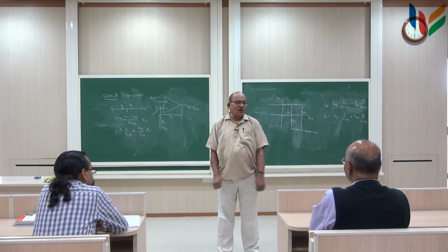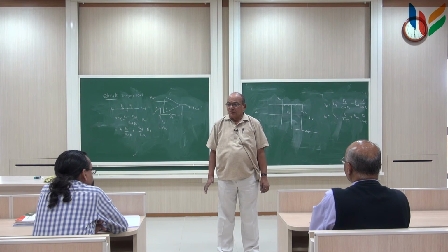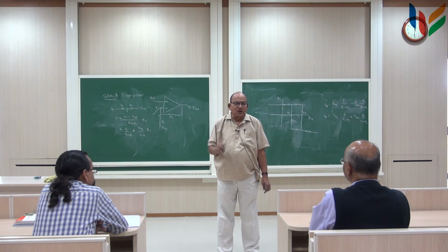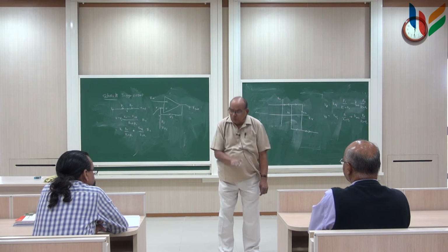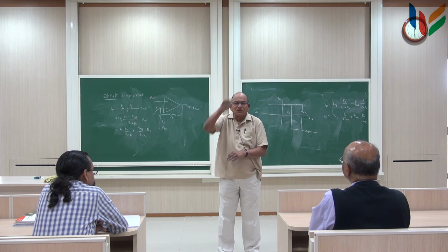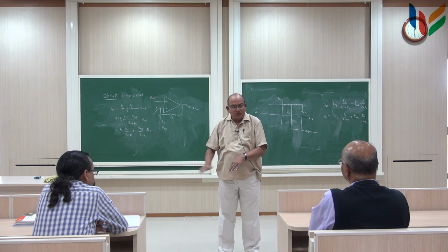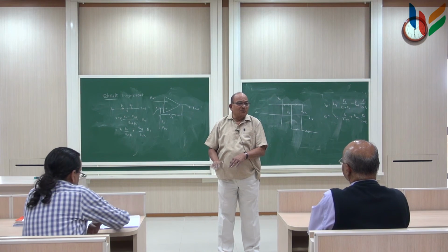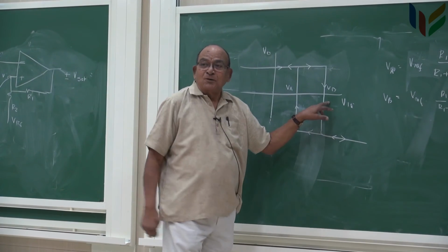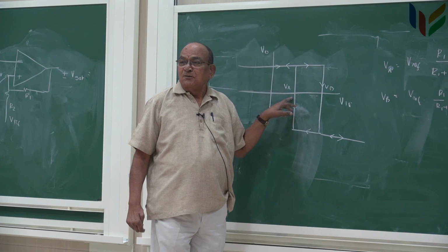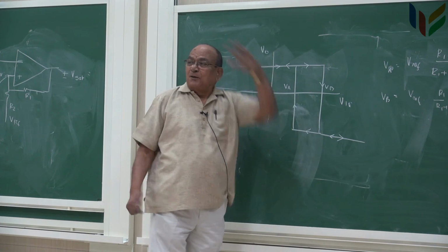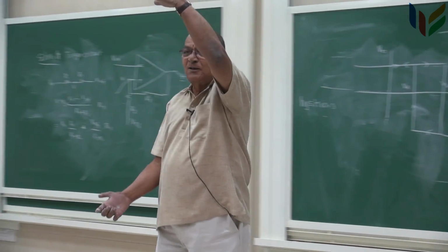Now, you want the water tank filling to stop when the height of the water goes beyond some value, and when it goes below some value, you want to start the motor. This value corresponds to shutting off the motor, and this value corresponds to turning on the motor, right? And you want it to be two different values because you want some height of the water in the tank.